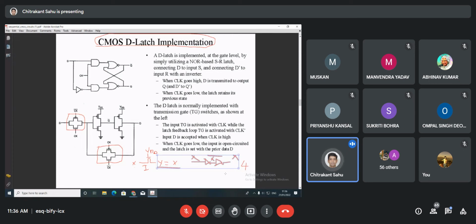So is there any way to design the functionality Y equal to X, equivalent to a pass transistor? That is called transmission gate logic. Whatever information is coming here, let's say information D, it will pass information D based on the gate's input. So the working is almost similar to a pass transistor.